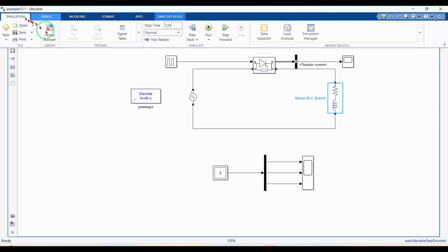You will notice that the inductive load smooths the output current waveform, reducing its sharp transitions. However, it also introduces negative spikes in the output voltage due to the energy stored and released by the inductor during each cycle. Now, add a freewheeling diode across the load to eliminate these negative spikes.